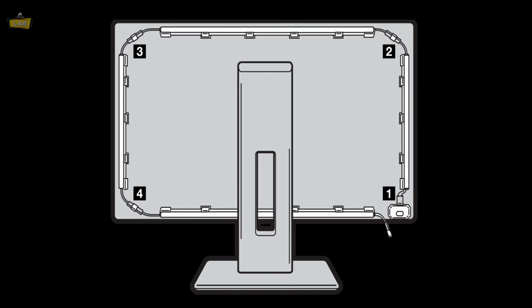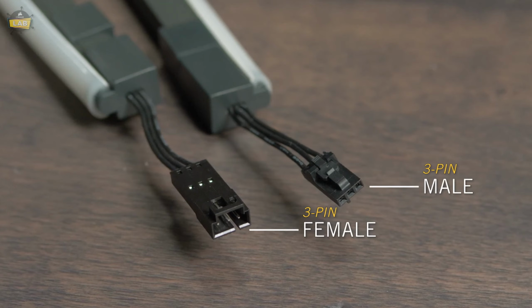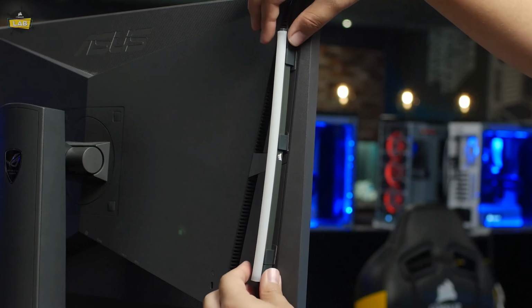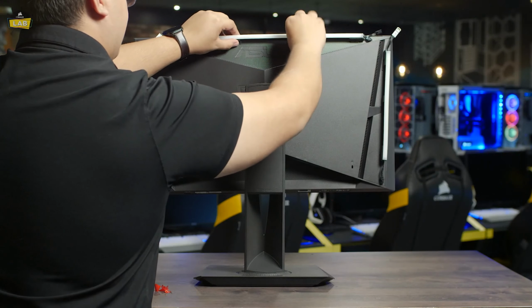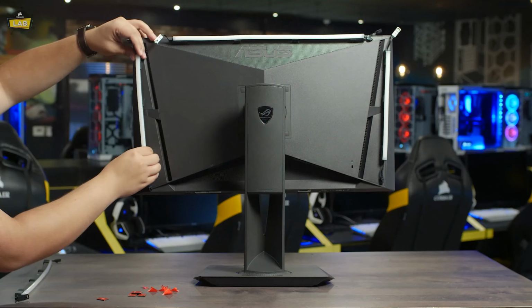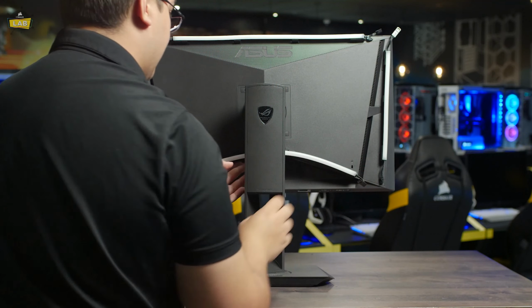If you're installing the LS100 starter kit on a monitor, follow this diagram to ensure the strips are in proper order. Remember that the beginning of each strip is a male 3-pin connector. With that in mind, the first LED strip in the chain should be a short 250mm strip along the right side of the monitor, followed by a long 450mm strip along the top of the monitor, another short 250mm strip along the left side of the monitor, and finally a long 450mm strip along the bottom.